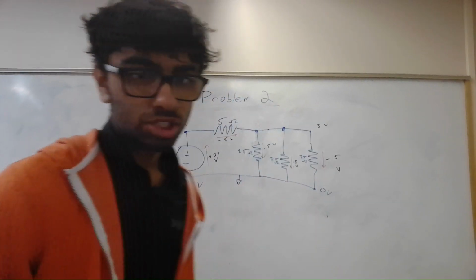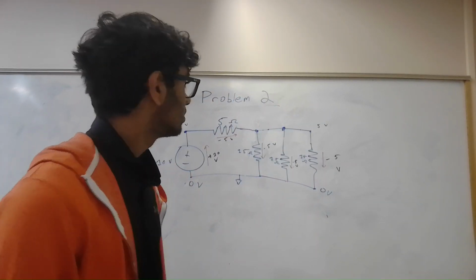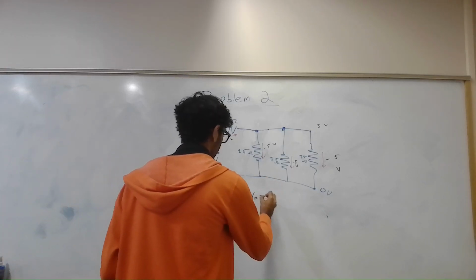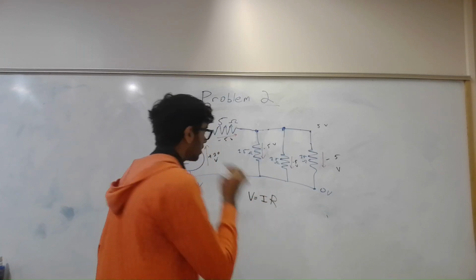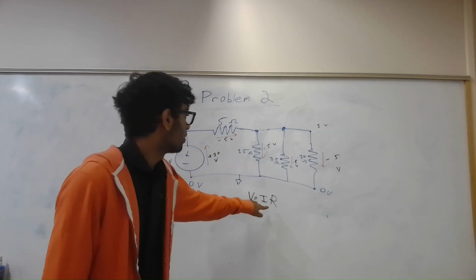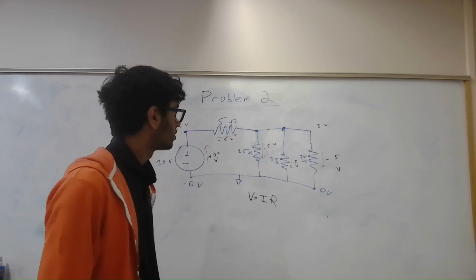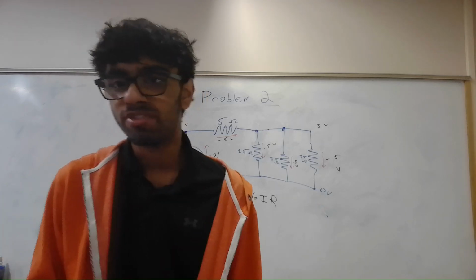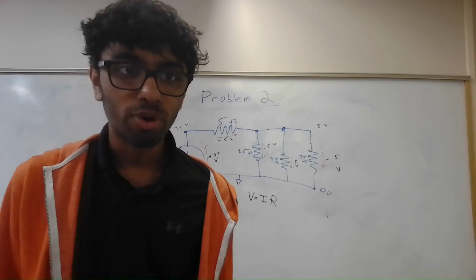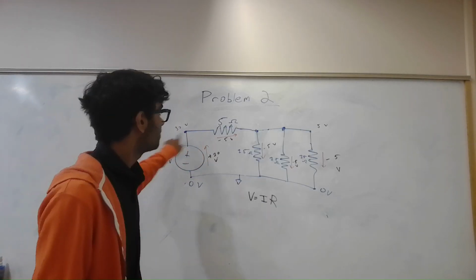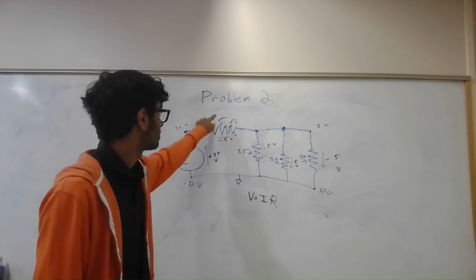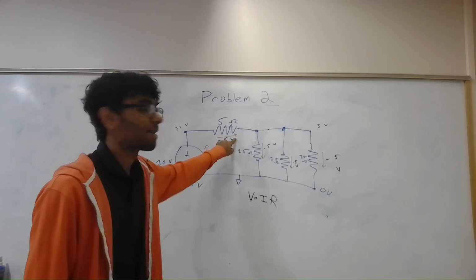So based on the voltage drop, what current flows through R3? Well, V equals IR. We know V, which is 5 volts, and we know R, which is 15 ohms. So 5 over 15 gives us a third of an amp. We did the same thing in the last problem. Through R4, 10 minus 5 is 5 volts. That's the voltage drop, right? 5 volts divided by 5 ohms gives us 1 amp.